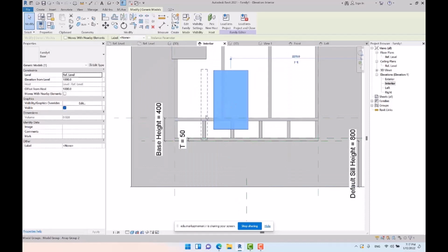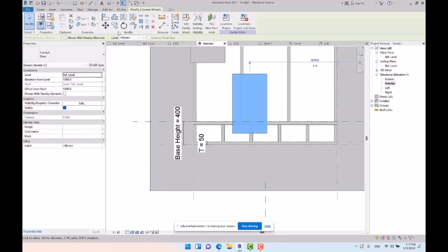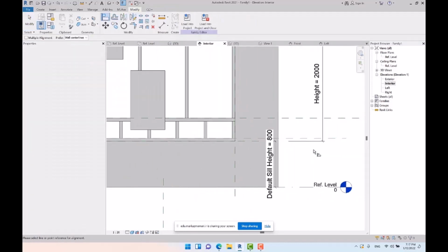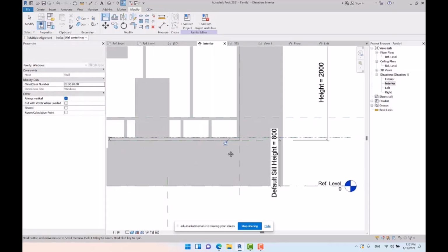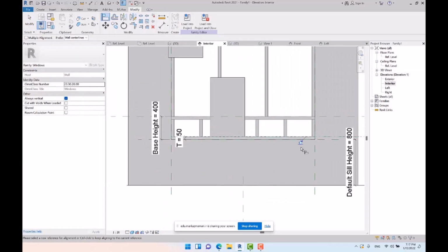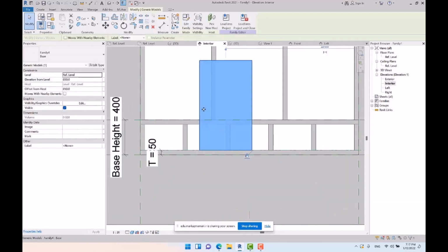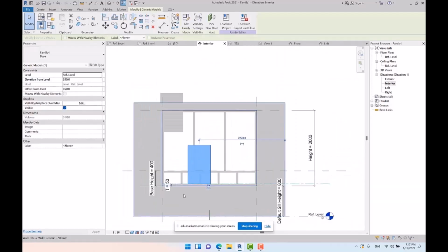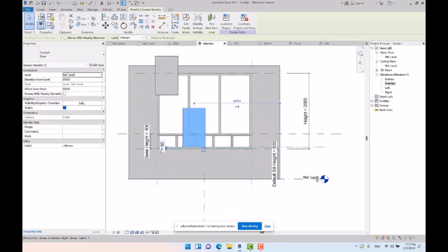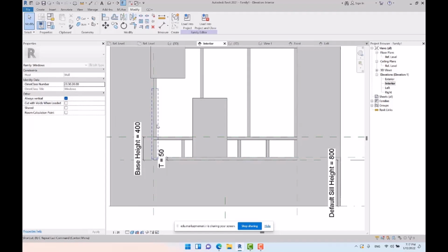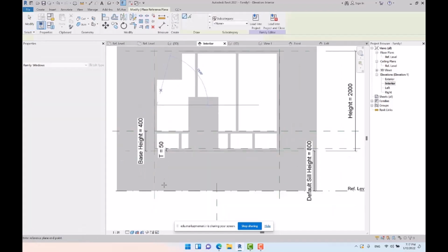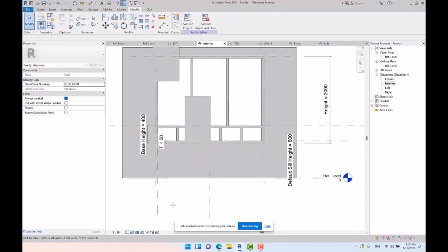As you can see, the bottom part is clear. I pick the align tool since I wanna align the panel, and then I lock it with the reference plane. Since the panel is going to be duplicated, the constraints will be removed. And after that, we need another reference plane at the left side, as you can see, but here there is no reference plane, so I extend this.